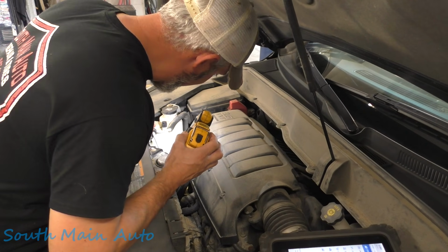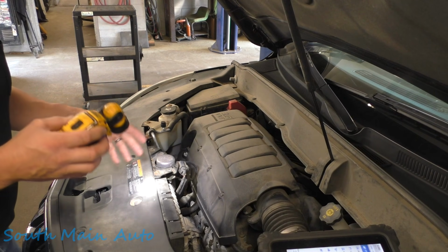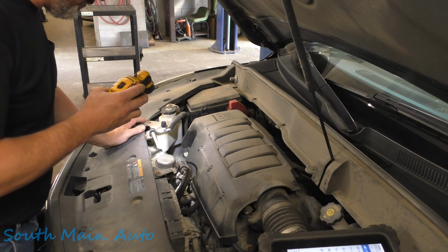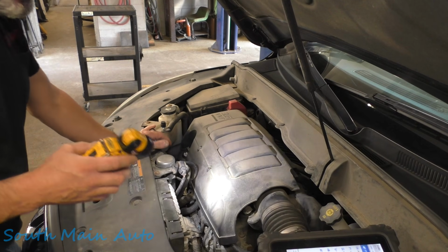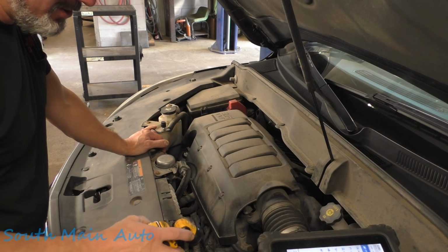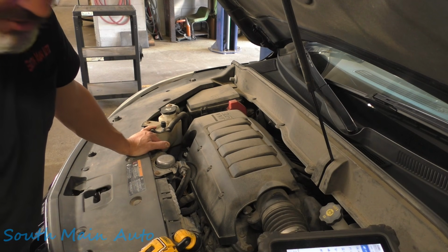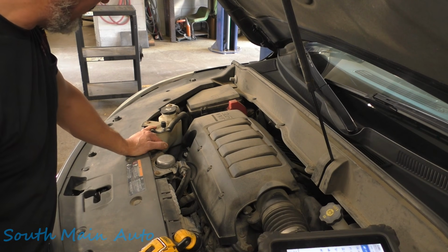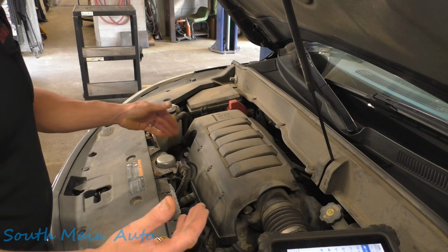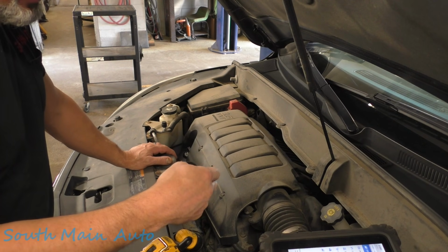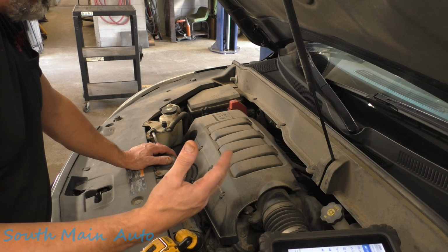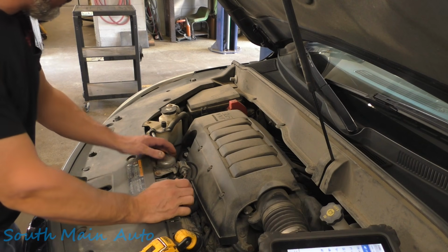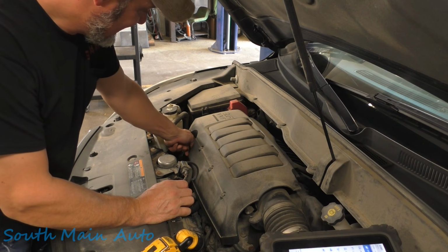Some things to keep in mind prior to doing that: obviously make sure it's full of coolant, the normal stuff. I was just speaking with the customer a minute ago, and she did state that she's been noticing the temperature gauge fluctuating up and down erratically also. So that aligns with that code. Said she'd just be driving along and see the gauge drop down and then go up and then drop down, and then a little while after that she'd get her engine light.